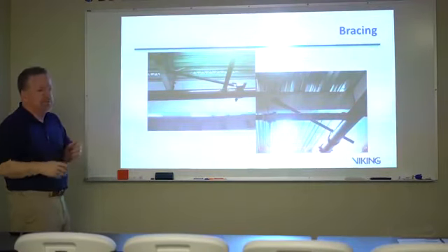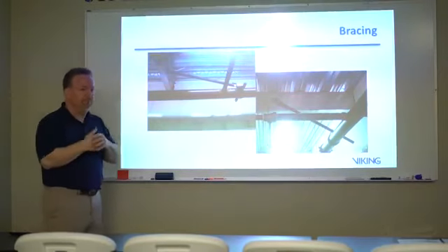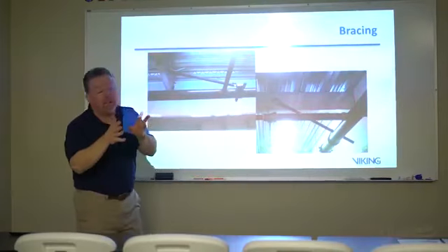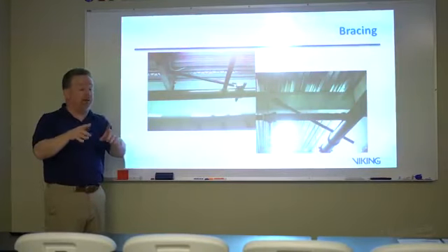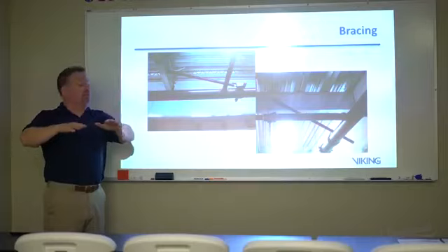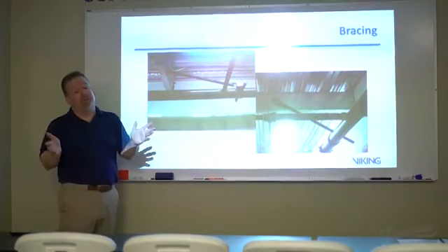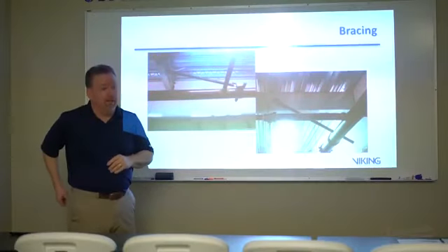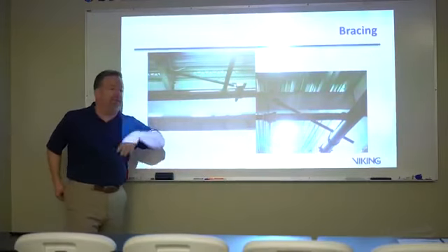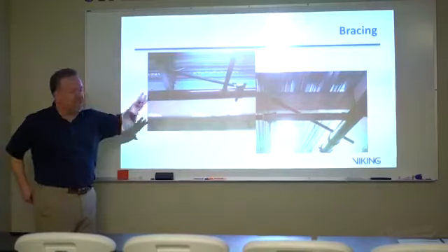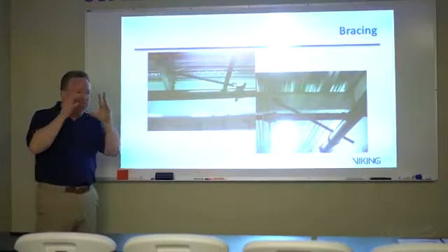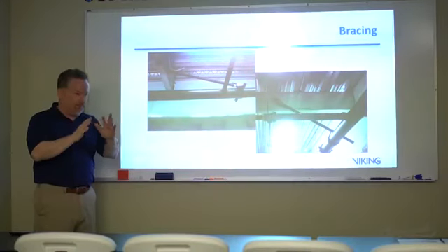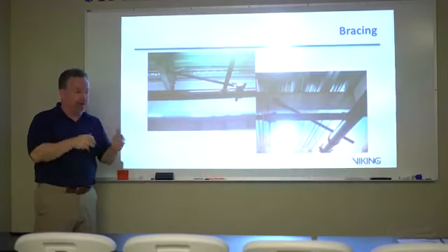You get up even into North Florida, and you're into zones that could require seismic bracing. Some of the military projects we do down here require it for blast. Military bases are going to require bracing simply because it's the military, and they build to what's called a mil spec. We're just doing it. These are high emergency buildings, very highly important buildings where we don't ever want anything to happen to the sprinkler system. So we're going to brace them.